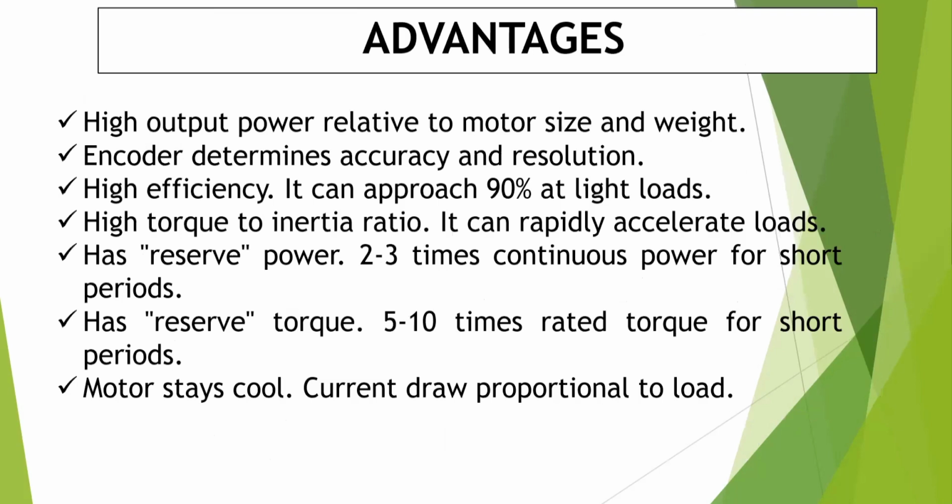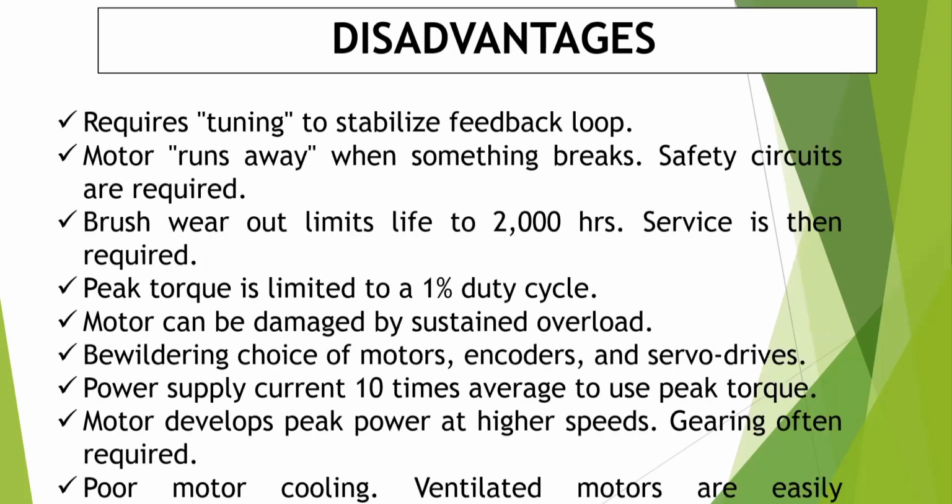Advantage: high output power relative to motor size, high efficiency. It can rapidly accelerate, reserve power 2-3 times continuous power. Reserve torque 5 to 10 times rated torque for a short time, and the motor stays cool. These are the wonderful advantages we will have.